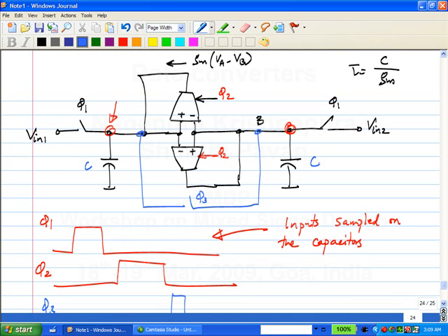Because I can rest assured that any real switch and any voltage controlled current source will have their own parasitic capacitance. So I don't need to explicitly put in any capacitance there. When I say the RC time constant, I'm talking about all the parasitic capacitances that will come in at those nodes because of all these components connected there.